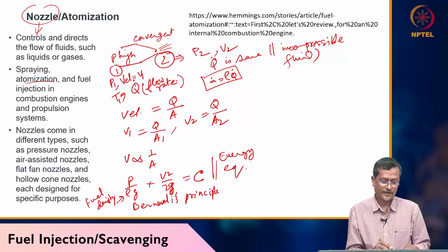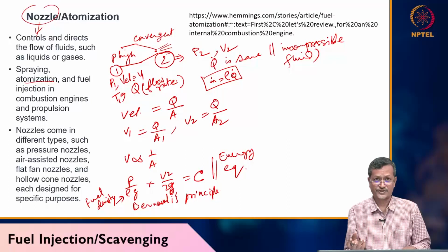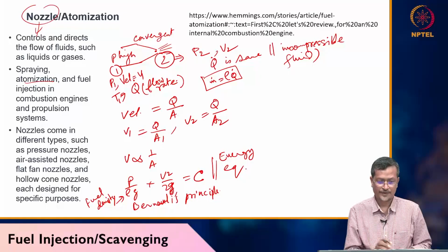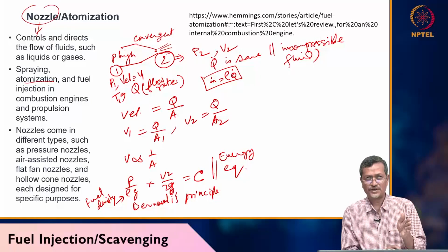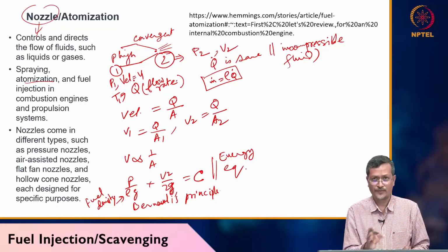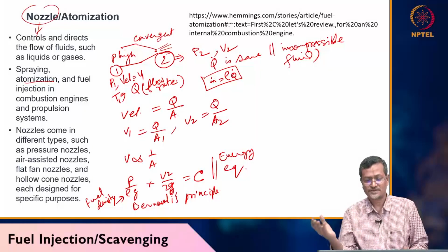For gasoline or petrol to be burnt in an engine, three things need to occur. It must be atomized. Gasoline or petrol or diesel also must be atomized, broken into small pieces, then mixed with air, then vaporization should be happening. So the carburetor will be preparing gasoline to make the phase change. But in my diesel engine or diesel cycle, I don't have a carburetor, I have direct fuel injection into the cylinder.